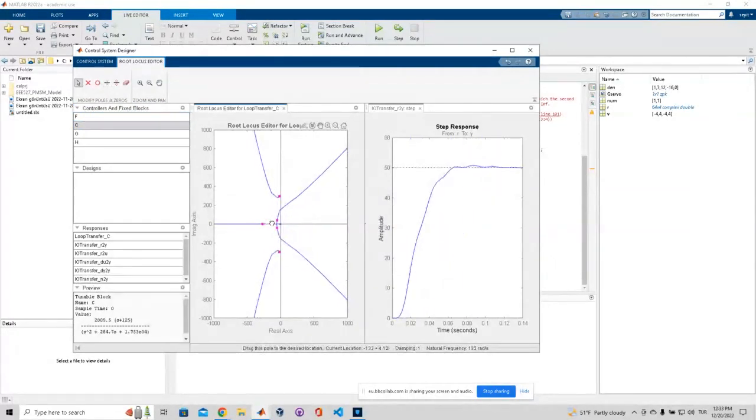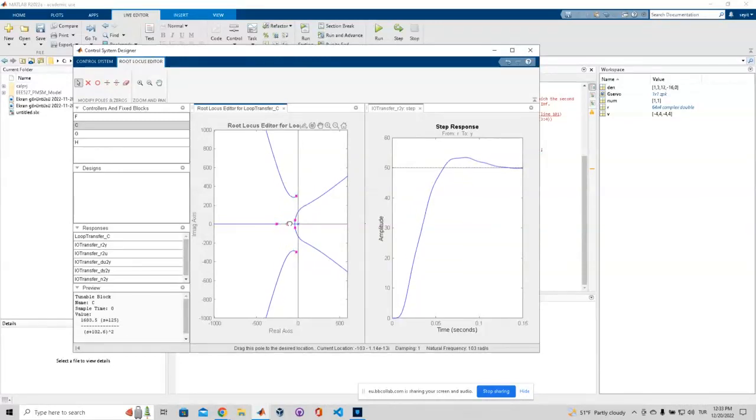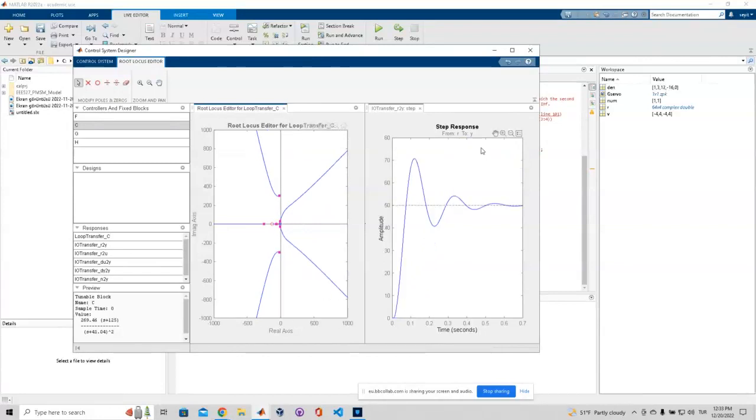See, in here our step response is not a good system. So when we add a zero and a pole near the origin, you see our step response going to more steady state. If we get closer to the origin, you see the overshoot is too much for us here. So we need to add the pole somewhere here. Yeah, you see the change in the step response.